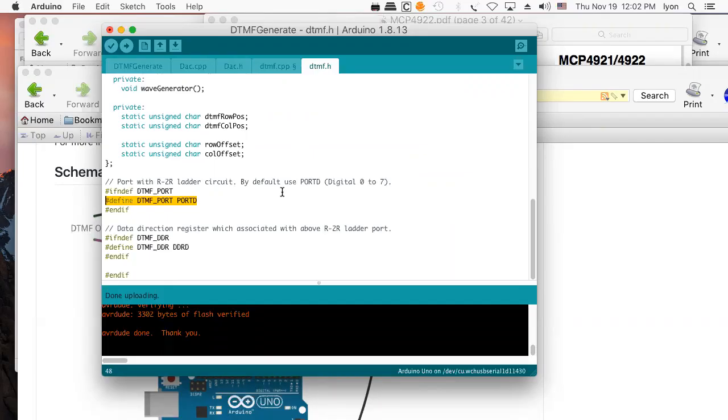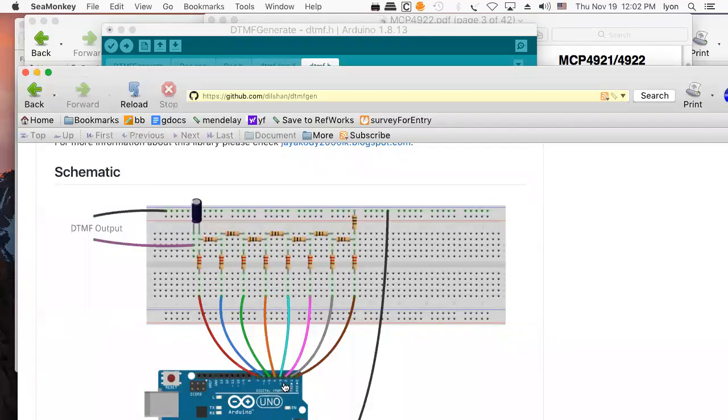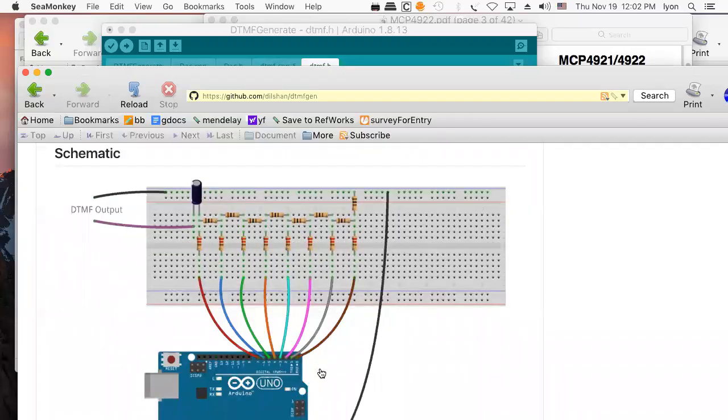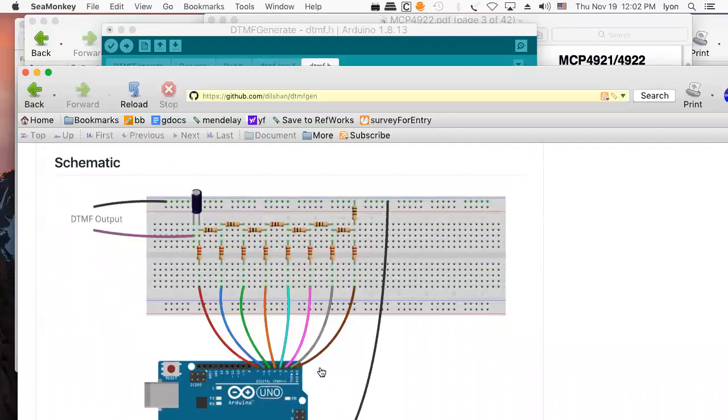So that's where he decided to wire everything because it was convenient. Then all he has to do is set it to some 8-bit number, and it just goes in one end and pops out the other and makes voltage. And that's it. And certainly you don't need a chip to make a DAC. On the other hand, if you wanted to make a 12-bit DAC, it ain't so easy to do with this setup because you're pretty much going to use up every single register on the whole thing. But still, it's possible. It's possible.